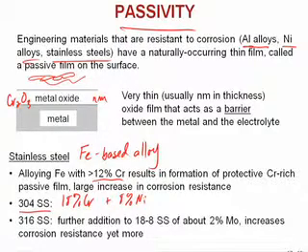You learned about the eutectoid transformation, where austenite, the gamma austenite, turns into alpha ferrite and cementite, Fe3C, or when they're combined, that's pearlite. So that happens at the eutectoid transformation temperature. If you add 8% nickel, that temperature goes down below room temperature. So the FCC structure is stable at room temperature.